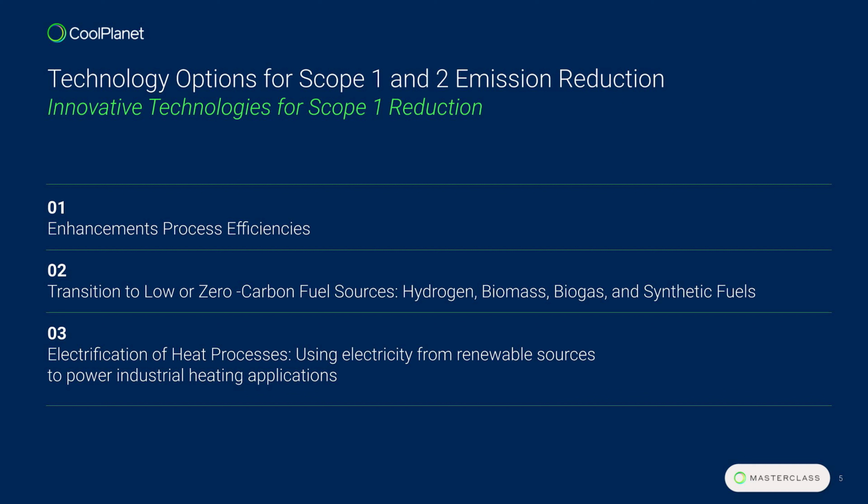Yeah, sure. It would be maybe alternative fuels that have less of a carbon impact. You're looking at biomass, LPG, bio LPG, hydrogen. You're looking at fuels that have a low carbon element to them, and you're consuming them on site. I suppose a negative towards them is their logistics and the space they require, storage and regulations around them, whereas the good part about them is maybe they can fit into your own combustion train. If you're still using steam on site, you can still burn the fuel to generate that steam. You don't have to change your manufacturing.